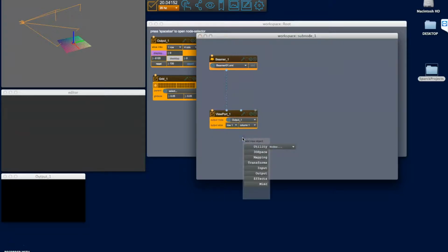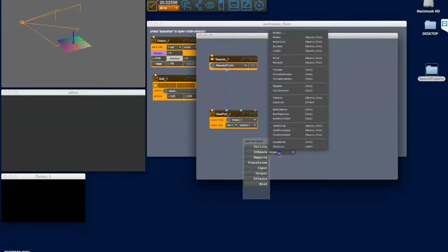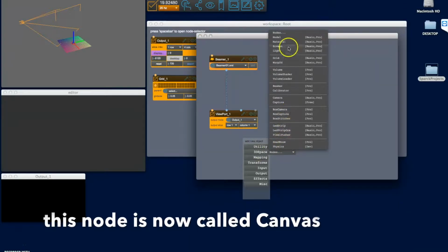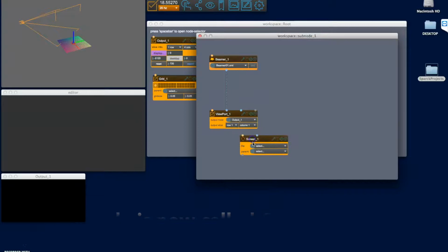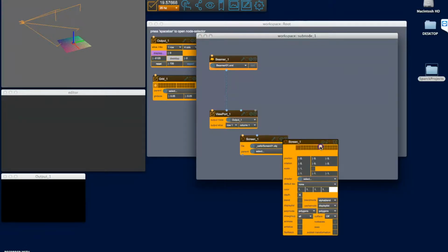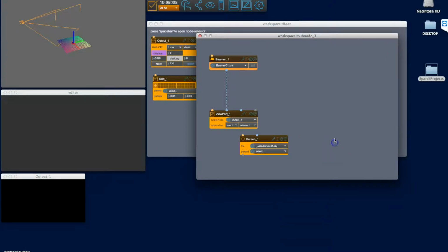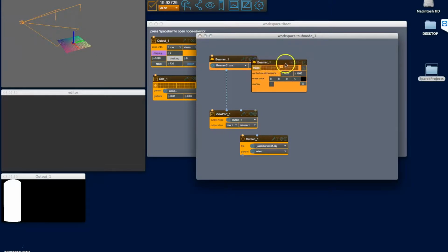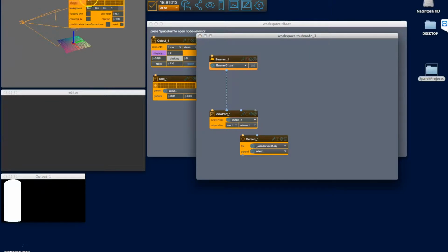Another piece missing, we need a screen object. And the screen object, I'm going to get the calibration screen object. And in here, I'm going to tell it that it is being drawn in this render group. And in here, we tell the beamer it should record everything that is inside this render group. And we can go to Tools, Stage, up here, and tell the stage it should show anything that is in this render group.